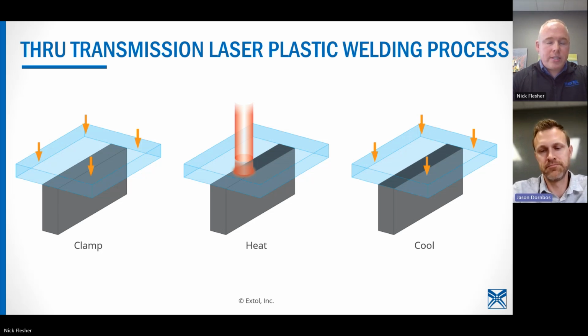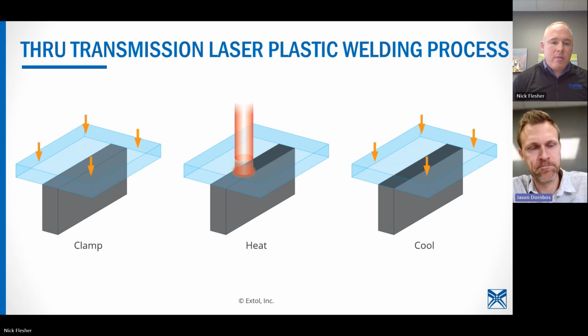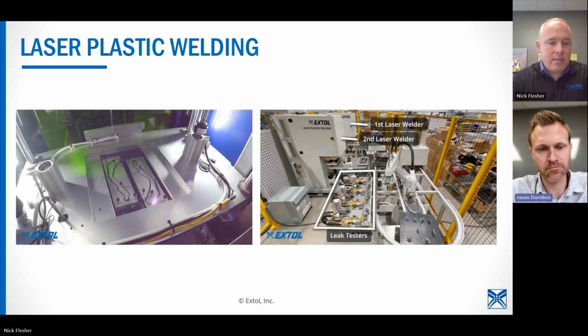The laser's transmitted through the part for true transmission, kind of in the name, but there are material requirements around the upper parts. They don't have to be clear like what's shown here, but there are material suppliers that will do an opaque material. And they do need to be designed properly so that you can get the energy all the way through it. So tons more information out there, but again, to focus on the integration of these kinds of systems, we're going to show 2 more videos on this one as well.